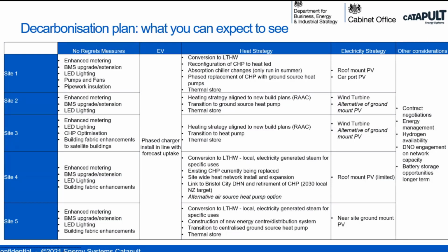So we've had to decarbonise sites' heating systems, and that's generally involved not entirely moving away from gas, but moving away from gas to possibly a hybrid system that combines heat pumps. We need to reduce the amount of gas use on site. So that's been a key focus, and reducing that gas use on a pathway of how you will totally decarbonise that site heating system, so how you might go about phasing that.